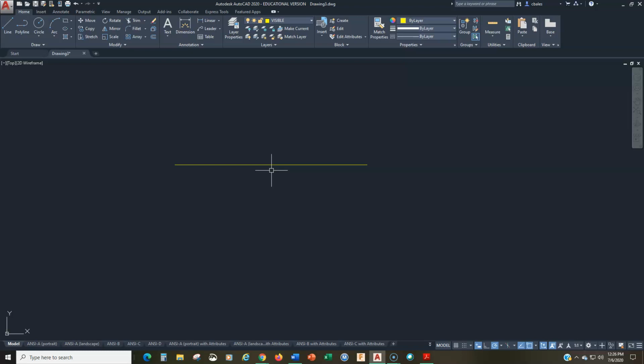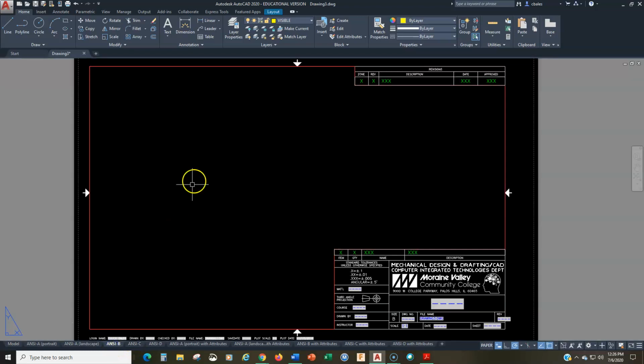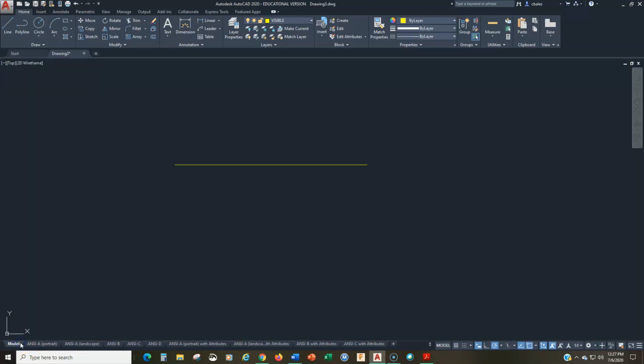The actual units, inches, millimeters, whatever, really come into play when we go to print a drawing, because this is where we say, hey, the thing that I drew, I want it to be 10 inches long, or 6 inches long, or 25 millimeters long. When we are actually ready to print the drawing, that's when we have to scale it accordingly. And what happens is we assign the units of our drawing to be whatever we want it to be.